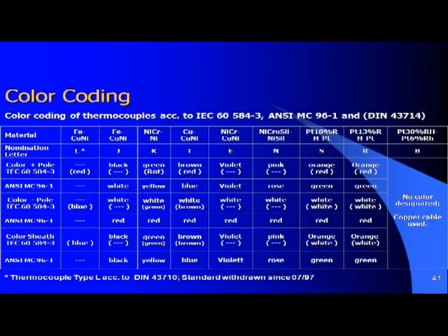And in the first column, iron, copper-nickel type L is a German specialty. It has the same alloy as type J, but a different characteristic. The difference is somewhere around 5 Kelvin per 100 degrees centigrade. It's not known outside Germany. It is not known and not used. Okay?